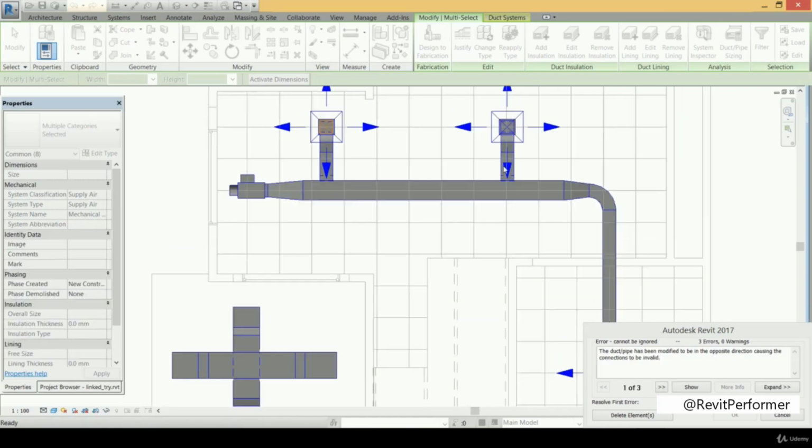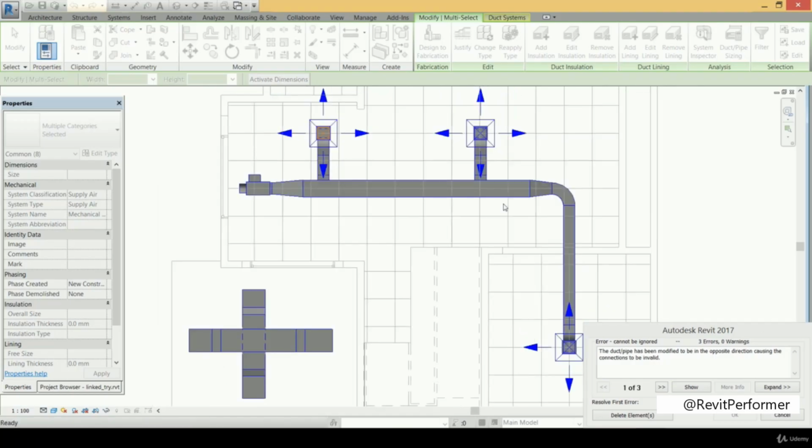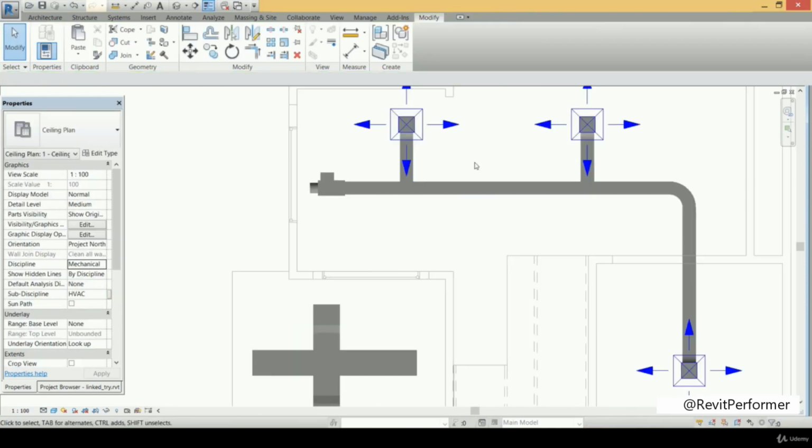while this branched duct will carry only the CFM of that diffuser, so it has a smaller size, and this duct, for example, has the same size as that duct because they will carry the same CFM, and also the same thing for that duct. Very good. So that's about the duct sizing method in the Revit software. Here we can press cancel, and that's it.